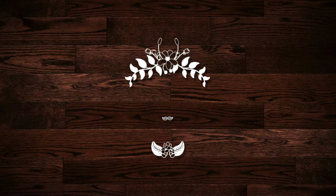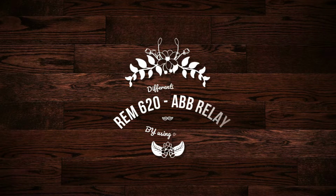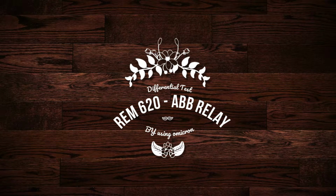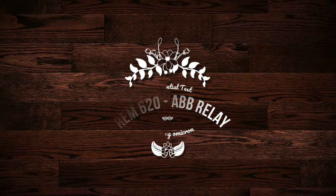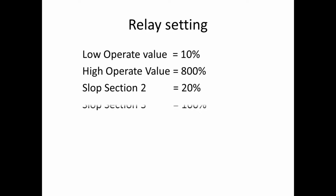I am going to show this motor differential test on the REM620 relay, which is an ABB relay, and we will see the relay settings now. Now we can see the relay setting. Low operating value equal to 10%, that is the differential pickup value. High operating value equal to 800%, that is the high set differential value.